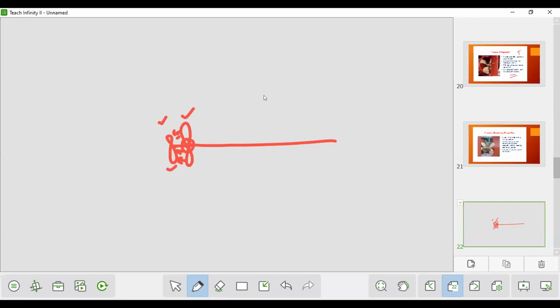Another feature is sharing of the load. The entire load of the propeller is shared by two propellers, which means the load on each propeller is reduced, so the propeller efficiency is good. That is the idea when we go for twin screw propulsion, triple screw propulsion, tandem propellers or contra-rotating propellers: the total load requirement can be shared between propellers, so the efficiency is good.